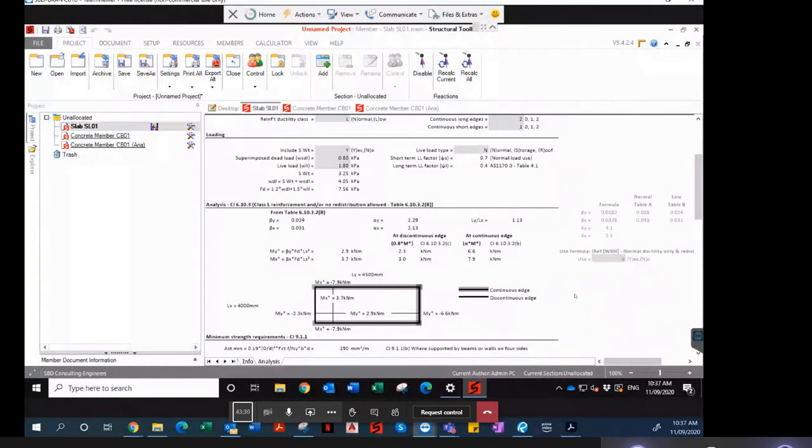Even with those point loads, we know that our 136 slab, even if I change it to 1 and 2, will quite easily work. Makes sense? So if we've got point loads, this is how you can work your slab. You can eliminate deep bed footings or bored piers underneath these smaller loads, because they can be taken by your slab. Our slab at 136 is